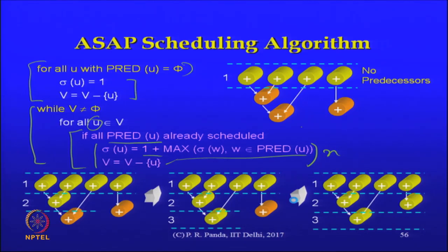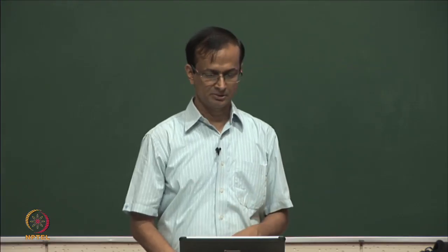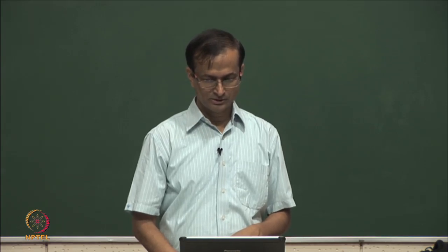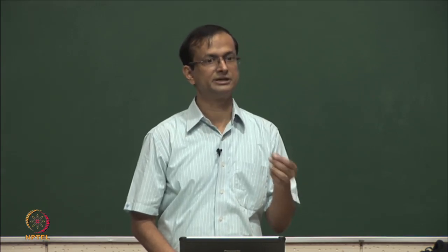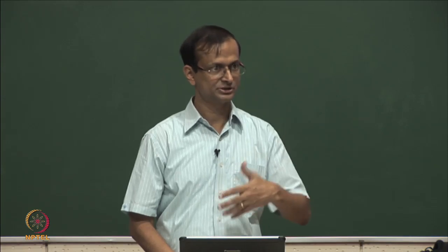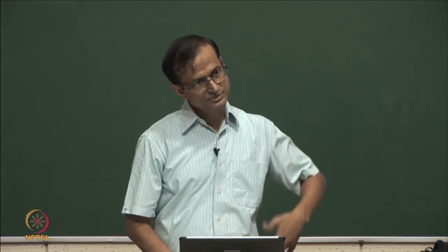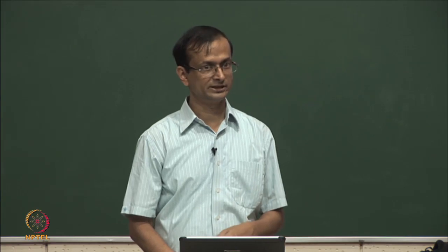What we have done so far is pre-processing. We just did the easy thing first, which is doing an ASAP schedule and an ALAP schedule, and the objective of doing that was that it revealed to us what range we really have, or in some ways it prioritized the nodes for us. Some of the nodes are more important to schedule, because if you delay some of the nodes, for example in the critical path, as you do the actual schedule, then all its subsequent nodes would get delayed.